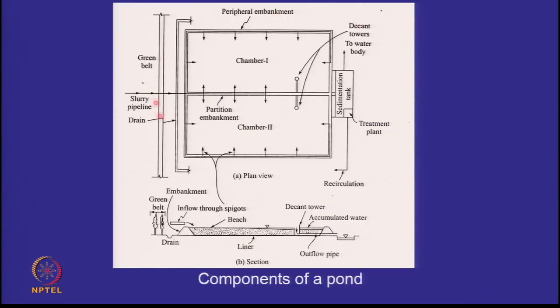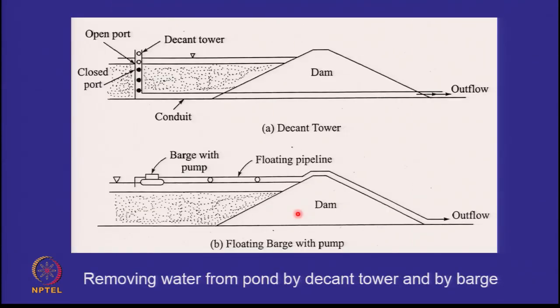Our main focus was on slurry ponds, so we looked at how to plan a pond, what it looks like in plan and section. We concentrated on how the leachate collection systems affect the stability of the dikes, whether they are close or far, whether fine material gets settled on the upstream side or coarse material, and how it affects the upstream raising stability.